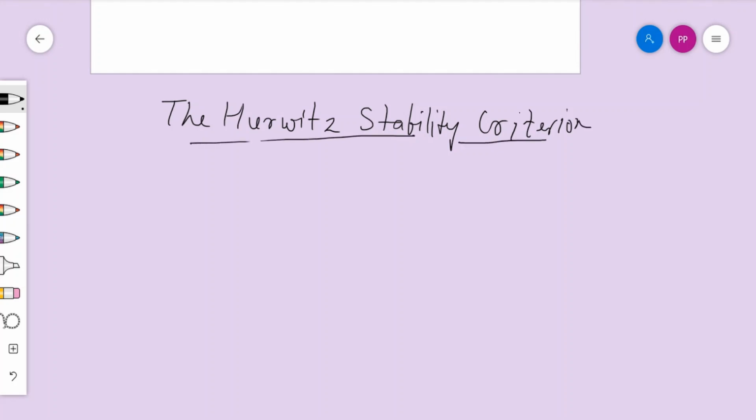So in the Hurwitz Stability Criterion, we obtain a Hurwitz array. Using that array, we obtain a matrix, and for certain parameters of the matrix we check whether the values are changing sign or not. A little more convenient technique to determine the values of certain parameters of system variables, which are the coefficients of its characteristic equation, we are going to learn. We determine whether the system is stable or not. So we'll study the Routh Stability Criteria, based on which we can solve the problems on LTI systems.